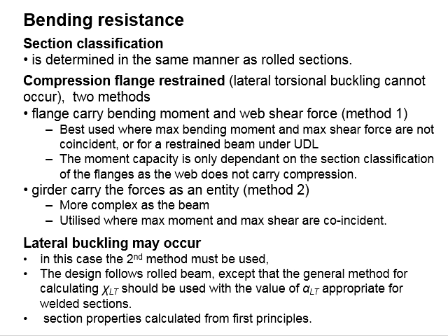To determine the section classifications, we can adopt a similar calculation process to a rolled section. When the compression flange is restrained, that means lateral torsional buckling does not occur.